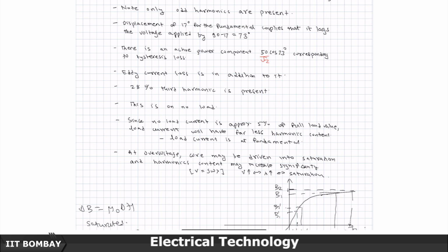The load current waveform is sinusoid; it is not dependent upon this iron element, it depends upon the load. If you have a voltage which is sinusoid, and there is a motor, a resistor, or a normal inductor connected, then the load current will always be significantly sinusoidal. So, the no load current adds on to it.